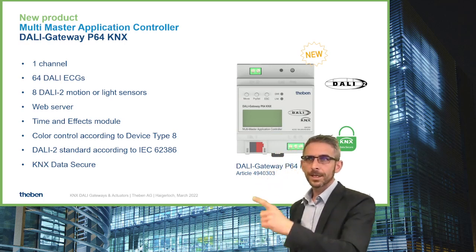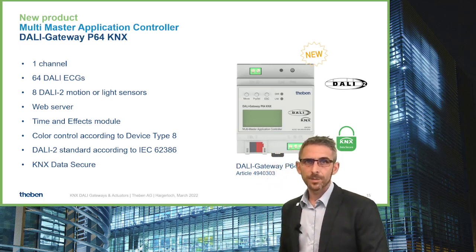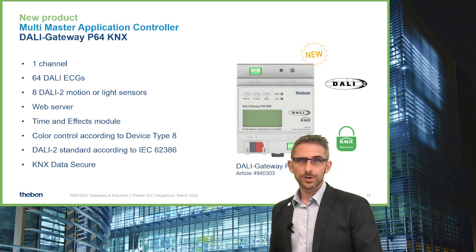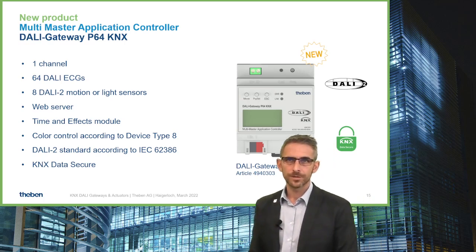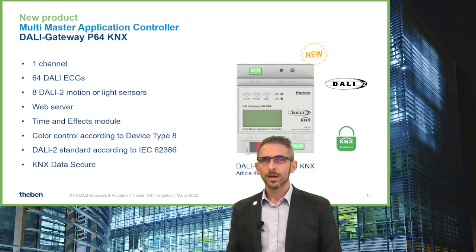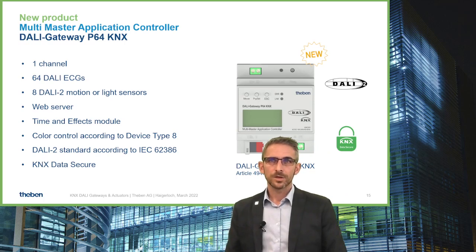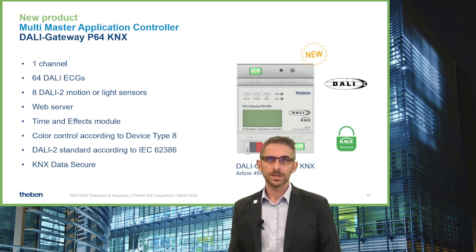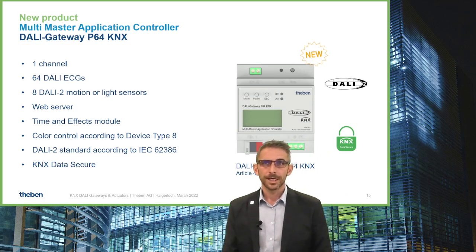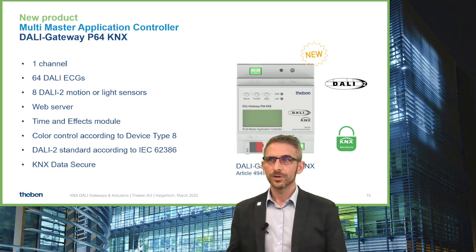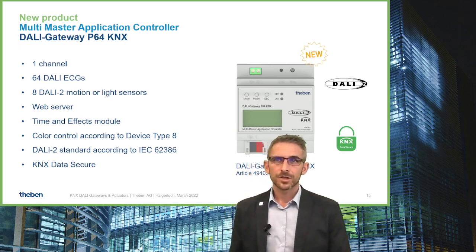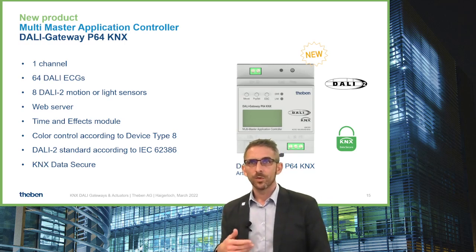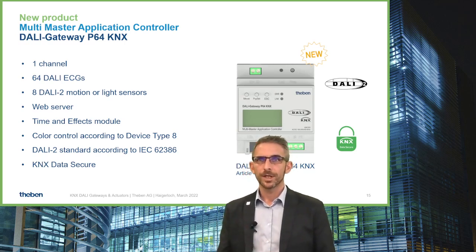Also included is a web server. The web server can be used for the DALI commissioning. So we have the possibility to do the DALI commissioning in the ETS with the device configuration app. Or we have the possibility to connect in the local network to the web server, and then we have the possibility to do the DALI commissioning and move around in the building, for example, to use a tablet, connect to the web server, go around and check which lamps has which DALI address, and to do the grouping and all this stuff.